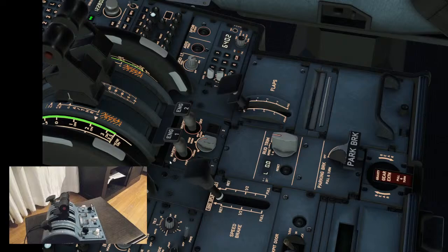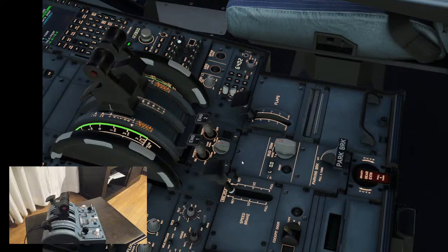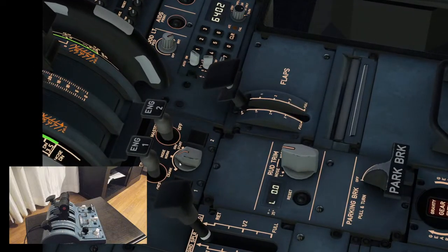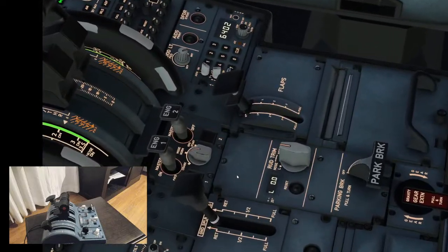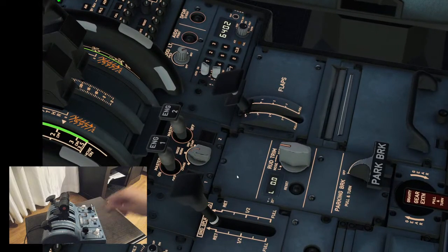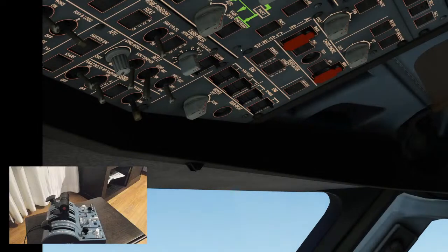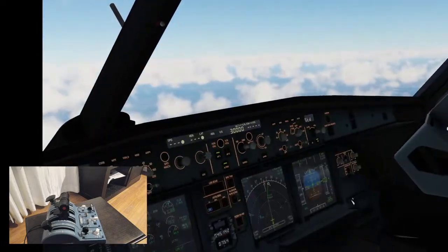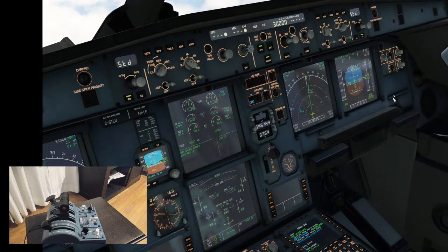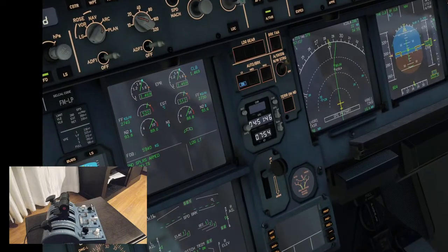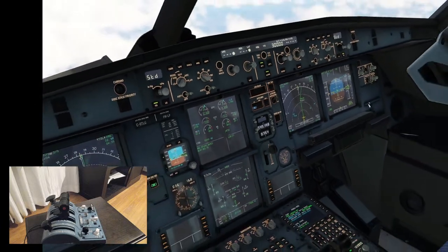I need to explain all the things regarding the crank. During long usage of the engines, they could be cleaned. During cleaning, we are taking this position. Here is the crank, and then we are setting manual here, and from the low speed, low revolution of the engine turbine turning, we are cleaning, and we are injecting some chemicals to clean the engines.